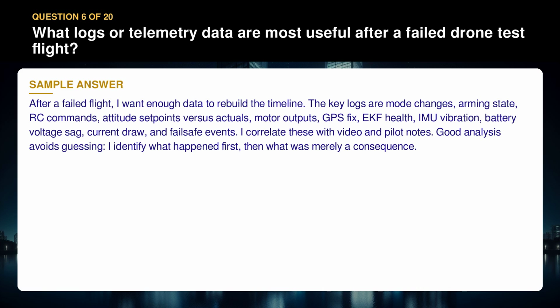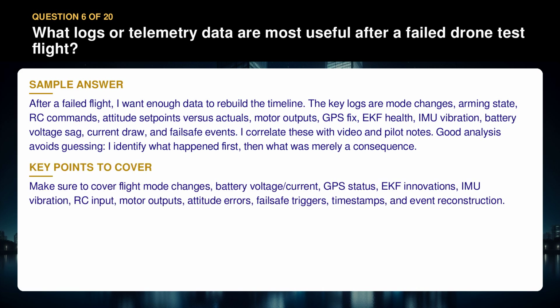Good analysis avoids guessing. I identify what happened first, then what was merely a consequence. Make sure to cover flight mode changes, battery voltage, current, GPS status, EKF innovations, IMU vibration, RC input, motor outputs, attitude errors, fail-safe triggers, timestamps, and event reconstruction.